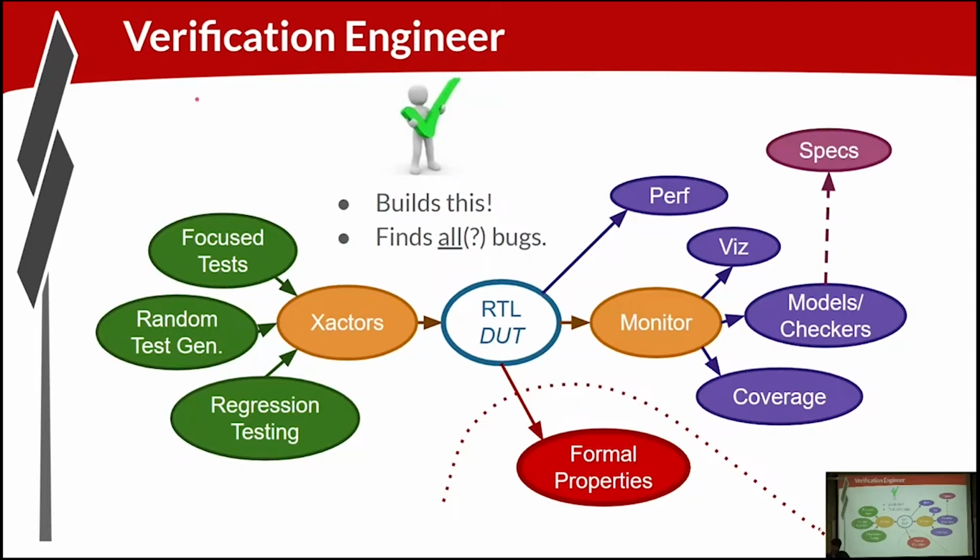The verification world is a bit more complex than the RTL world. Verification tends to deal with a myriad of languages, different tools, environments, and ways of approaching a problem. So in general terms, the verification engineer is creating the test bench. That's everything surrounding the RTL. That includes transactors that are driving stimulus into the RTL. The tests define what that stimulus needs to be in some way. For the CPUs that you designed, that would be a test program. The transactor is responsible for applying that test program to the model.